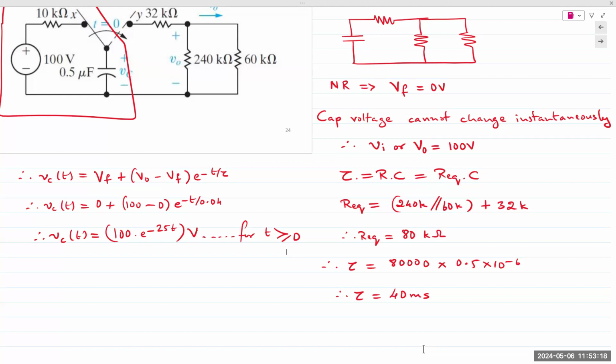It doesn't take the exact characteristics of a source. So the question being asked is, if the source is, let's say in this case, 100 volts, and the initial value would not be 100 volts. Yeah, that would certainly be the case. It depends on the circuit. Yeah, it could be like a Thevenin. You'd have to find a Thevenin equivalent network and then determine what the voltage or the current is for that component.